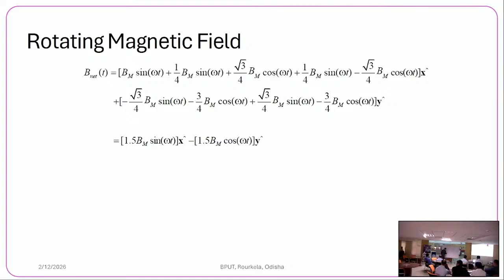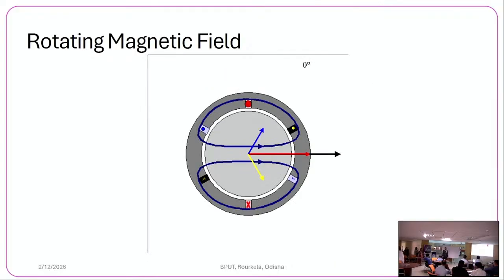Where, what is Fm? That is the number of turns into the maximum current. So this is the resultant MMF at time t equal to 1. Its magnitude is 3 by 2 Fm into Im, and the direction is in this direction. Okay. Then after some time, say you do the same thing again. Its magnitude will be 3 by 2 Fm, but its position will be different.